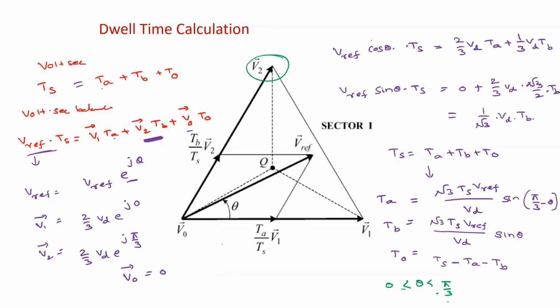Now, if you divide this into two parts, this angle corresponds to 30 degrees. This green one corresponds to 30 degrees, because this overall angle is 60 degrees. Now which vector is influencing more? That is what we want to study. This is helpful when you are going for higher levels. For example, if the overall voltage vector falls in the 0 to 30 group, or there is another scenario where the resultant vector or the V reference falls in the 30 to 60 degrees group.